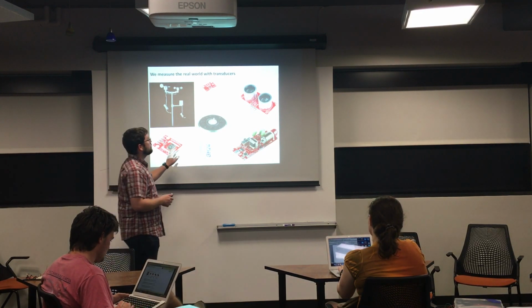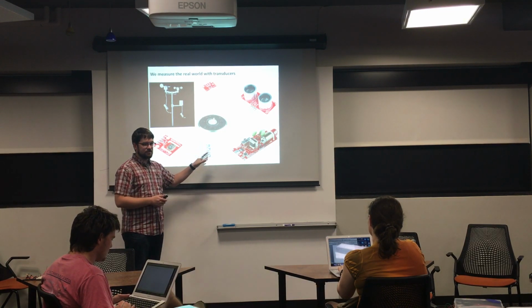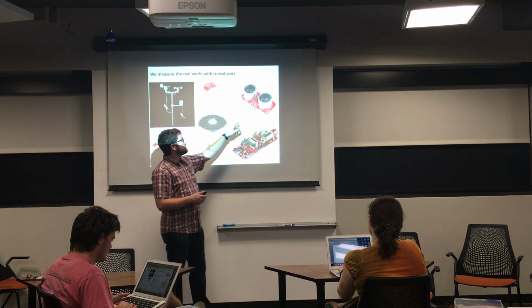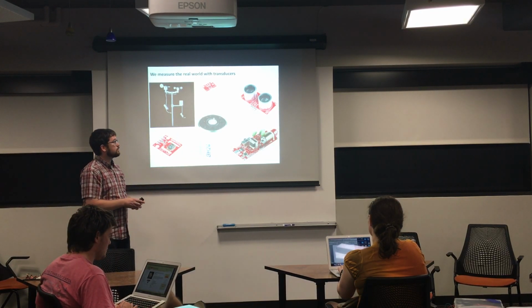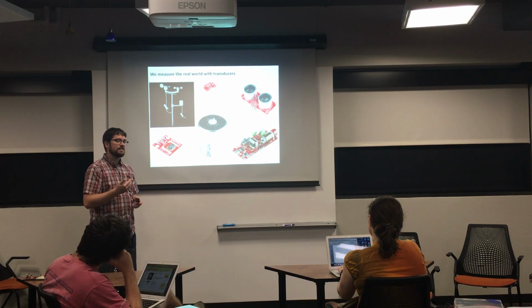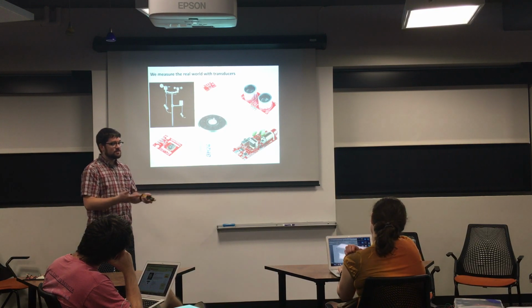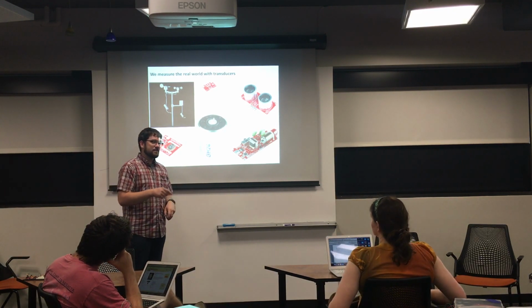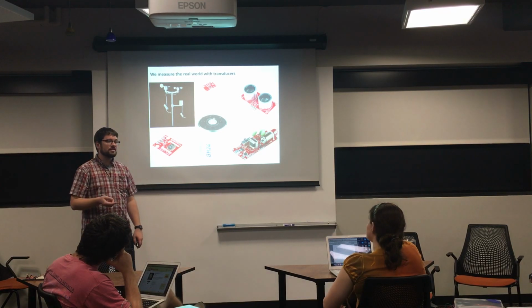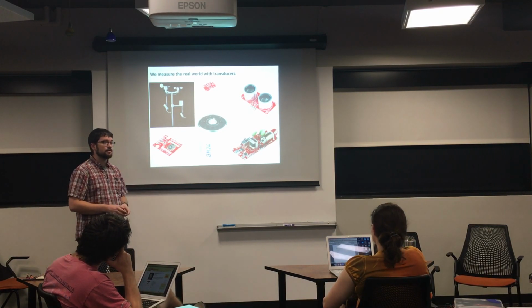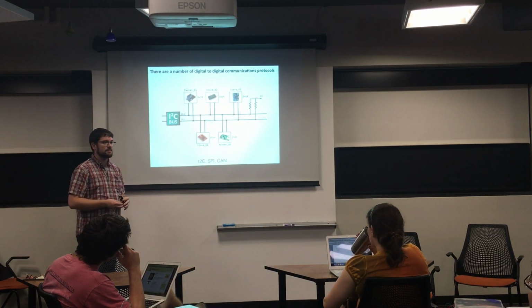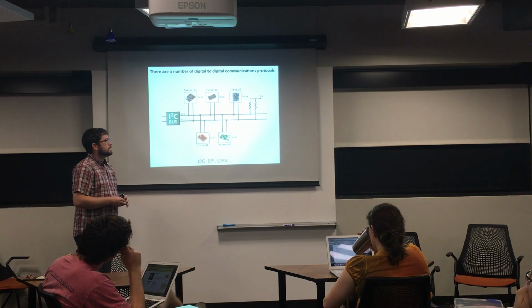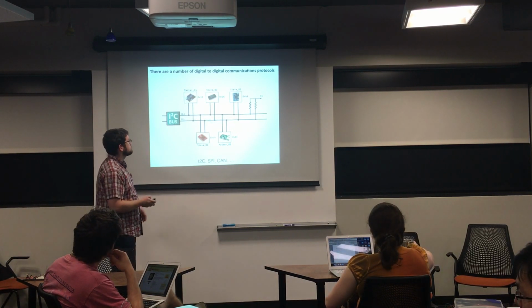And this is one place where you have to know everything that can affect your transducer. If you point this at something stationary, say I were to set it up on a tripod and point it towards the wall and record it for a few days, you would see it looks like the wall moves back and forth in a very systematic fashion, which we know it doesn't. It's because the speed of sound varies with temperature. In fact, it's 0.6 meters per second per degree Celsius, and so it's going to affect your readings if you don't correct for it. Almost every transducer has some kind of temperature dependence, and it's generally pretty awful to try to do corrections in-house.